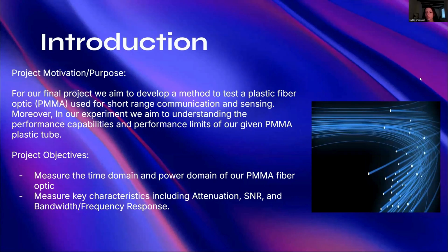All right, for our project, we wanted to develop a method to test a plastic fiber optic used for short-range communicating and sensing. For our experiment, we wanted to understand the performance capabilities and performance limits of our plastic tube. Our objectives were to measure the time domain and power domain, and also measure the key characteristics, including the attenuation, SNR, and the bandwidth frequency response.